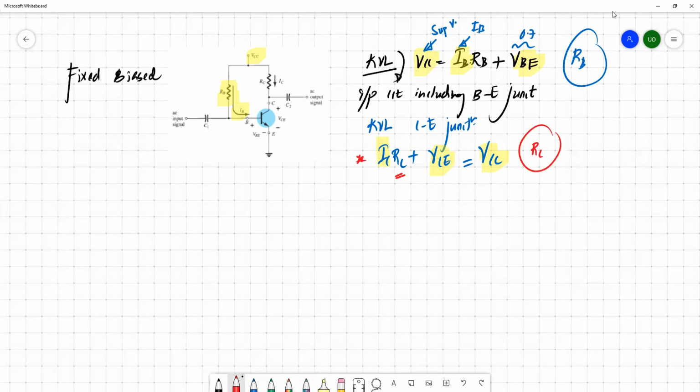So this is a very simple mechanism. You can take part of the voltage through this RB, the base resistor, so you can make the base emitter junction forward biased through this RB resistor. It's connected to a single external source and powers the base emitter junction as well as the base collector junction.